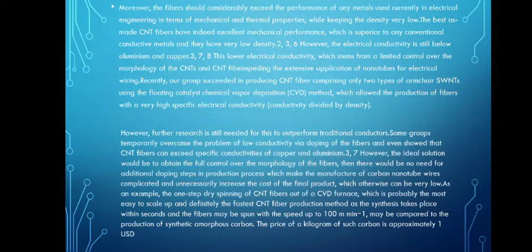The best made CNT fibers have excellent mechanical performance, which is superior to any conventional conductive material, and they have very low density, 2-3. However, the electrical conductivity is still below aluminum and copper. This lower electrical conductivity stems from a limited control over the morphology of the CNT and CNT fiber